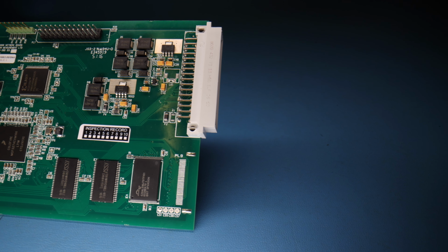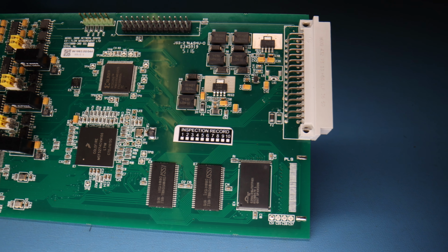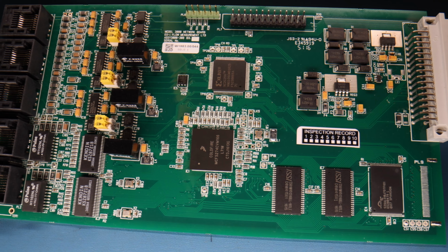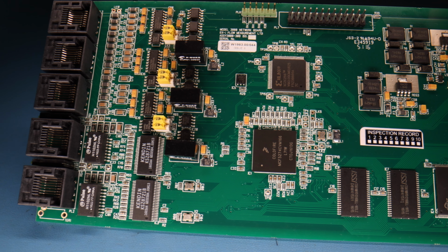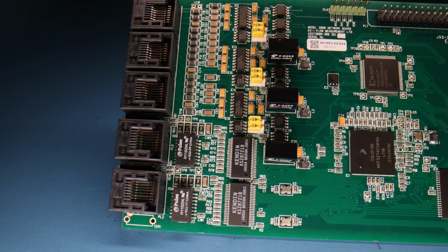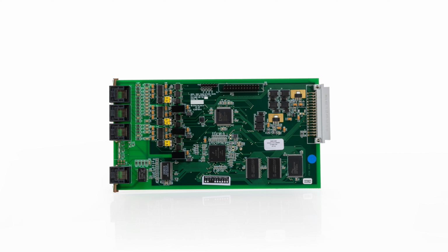Communication boards come in 2 variations. Functionally very similar, the main difference is 1 or 2 Ethernet ports. Both have 3 magnetically isolated RS485 and RS232 serial ports, one of which has RTS and CTS signals for older printers. The 3000-305 communication board has a single 100 base T Cat5 Ethernet.